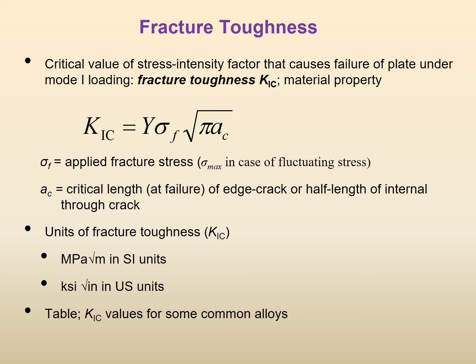You increase the applied stress further. Then the stress intensity goes further and the crack grows a little more. Does it still crack? Yes, suddenly it cracks. So you kept on increasing the stress intensity K1, and after a certain critical value, it will suddenly crack. So that critical value of stress intensity is the fracture toughness of the material.